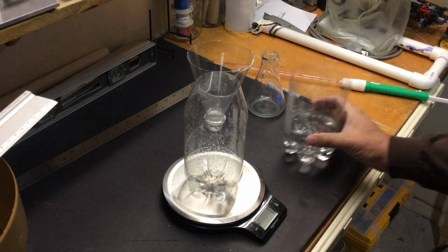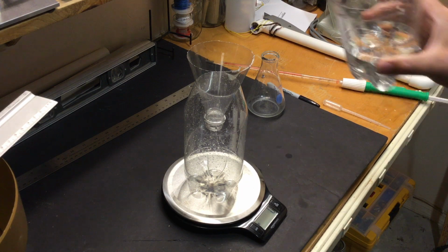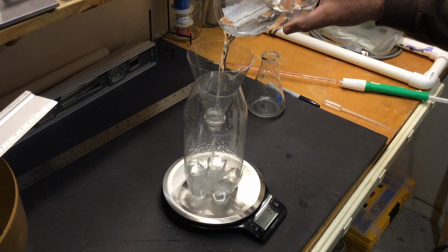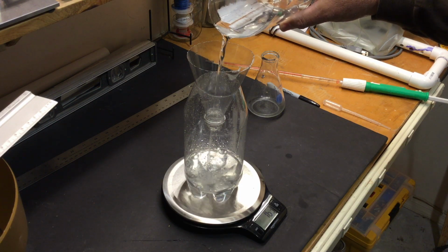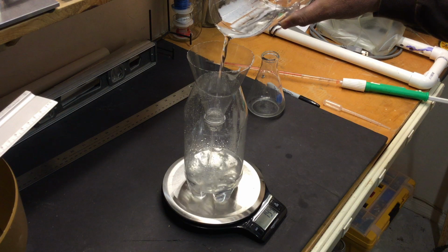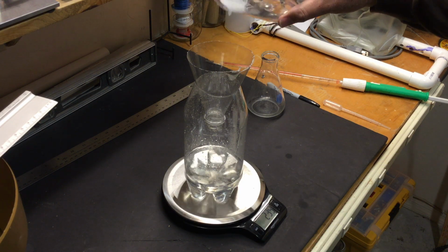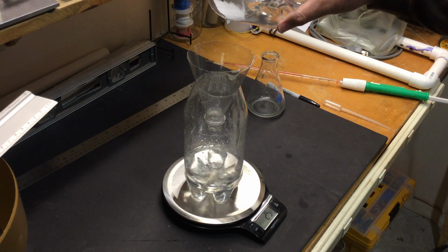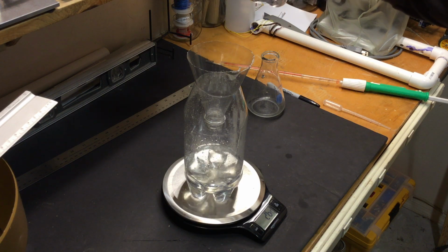Okay, folks, so I'm going to do the same experiment this time with the tipping bucket rain gauge. This time I'm going to need to measure out 275 grams of water, and that mass of water should yield 50 millimeters or 5 centimeters on the tipping bucket rain gauge, calculated from a total of 179 tips.